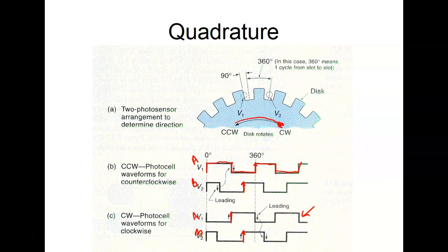On the robot, they don't have any special speed sensors. But when you deal with a linear or circular move, you specify the speed of the tool center point. You might say I want it to move 100 millimeters per second. Well, how in the world does it know the speed? The controller is looking at the rate of the pulses coming back, right? Does that make sense? This is what's nice about these incremental encoders, especially quadratures. We get three pieces of information off that encoder: the position, the direction, and the speed.